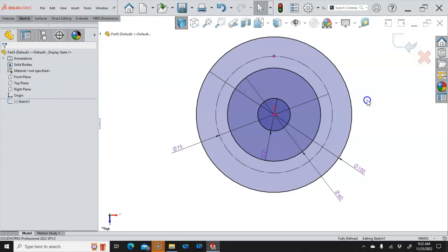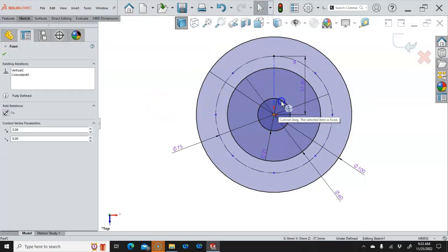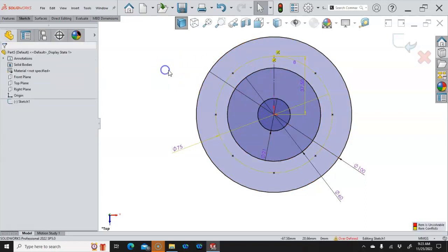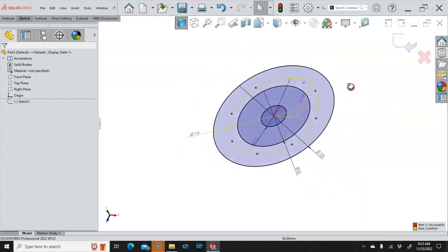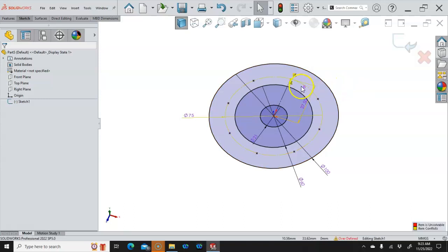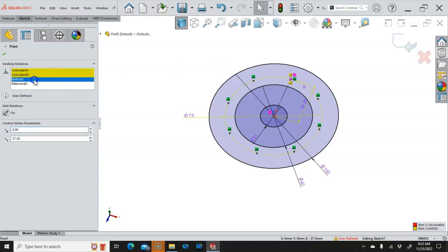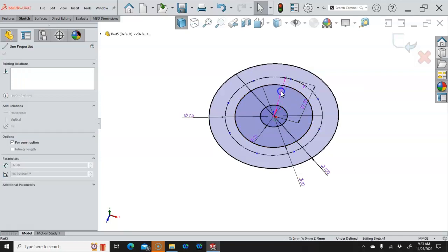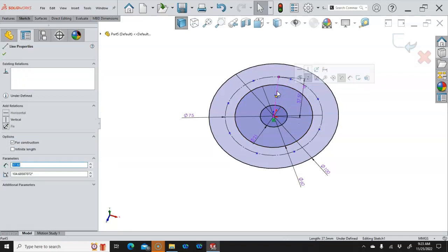We had a total of 8 of those, and my equal spacing and dimension radius are turned on, and we'll go ahead and accept. And it is not liking that one, so let's see if it goes that one. All right, so it added something there. All right, so it's probably not liking the vertical. Coincident. So if I go back to that and we take off the coincident, no, how about one of the coincidents? All right, so the vertical probably could have stayed then.